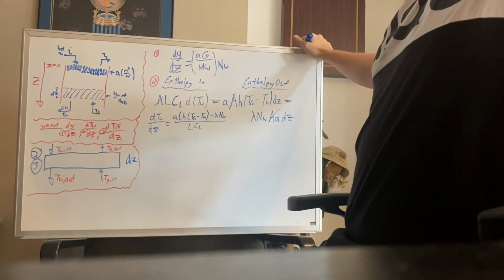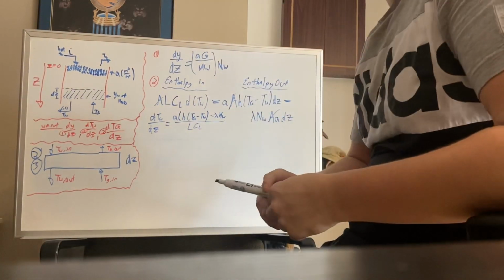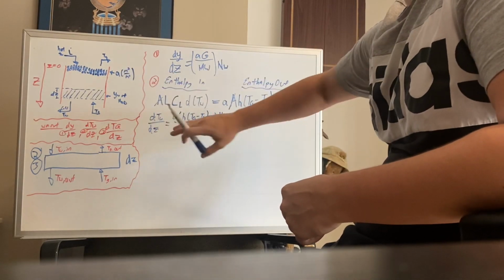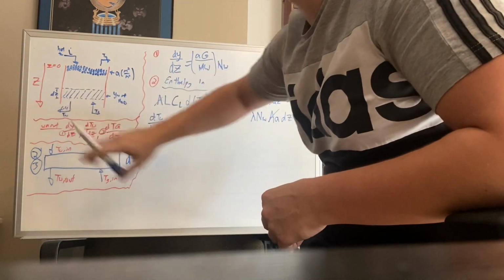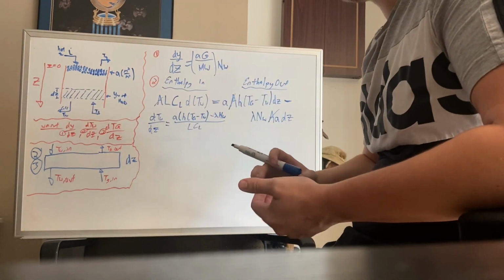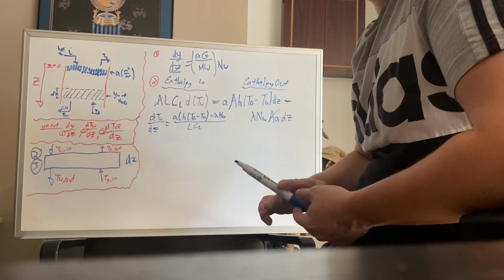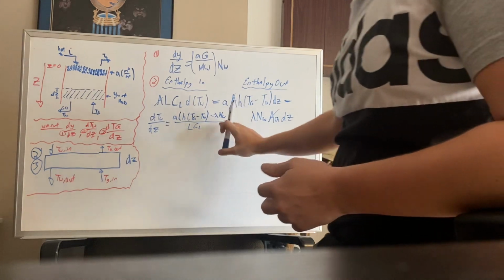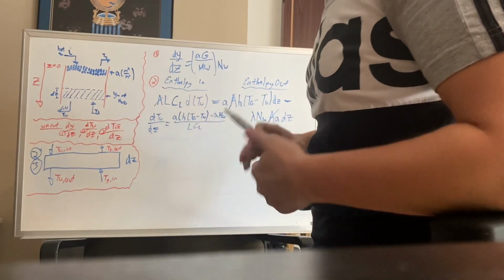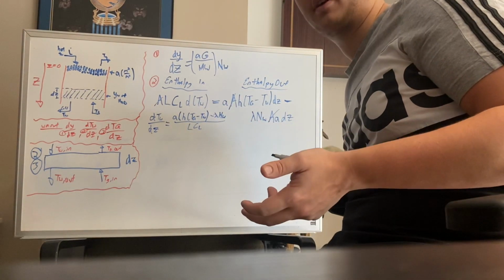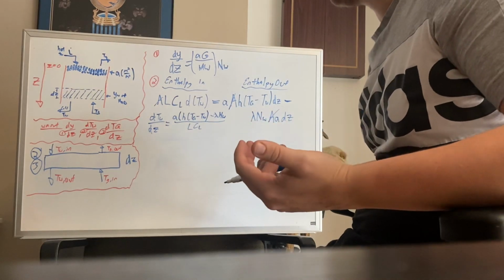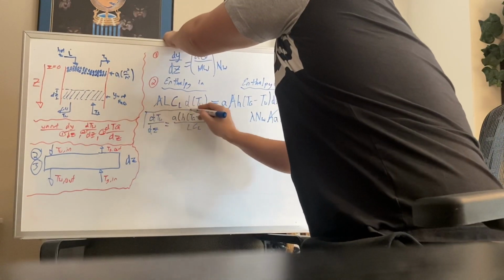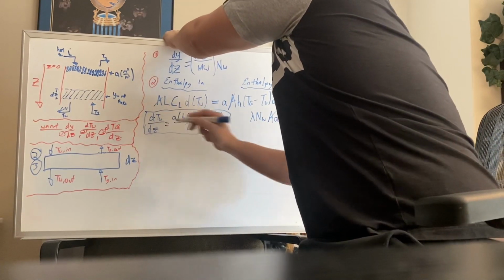And so this describes the temperature change of the water that is taking place in the cooling tower with respect to it traveling through this area designated dZ. And that's going to make sense, just because it's going to be cooling off, it's going to be losing that temperature. And so subtracting off this heat of vaporization multiplied by the molar flow rate of the liquid makes sense, because it's going to be losing some sort of energy as it evaporates off. And that is actually going to solve it for the second differential equation we are going to need